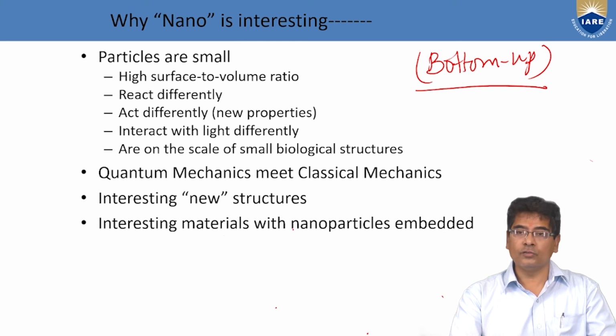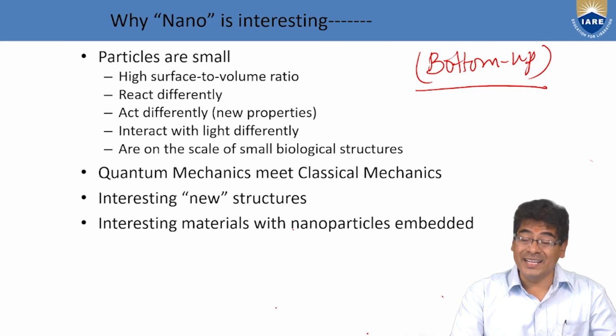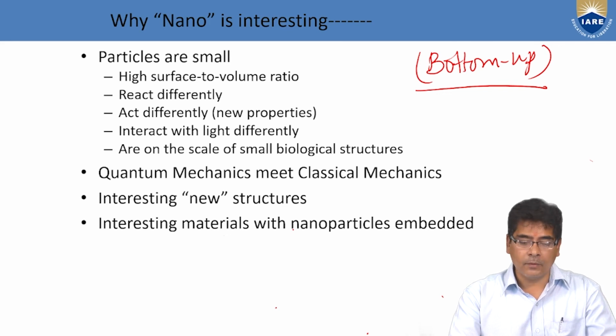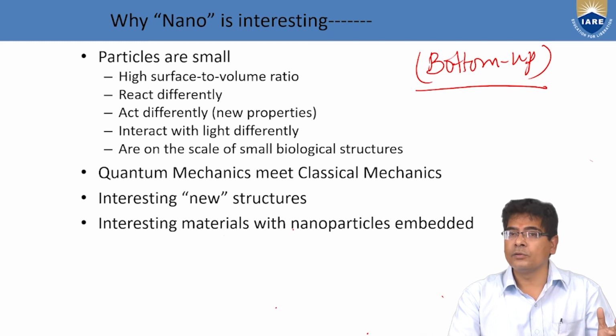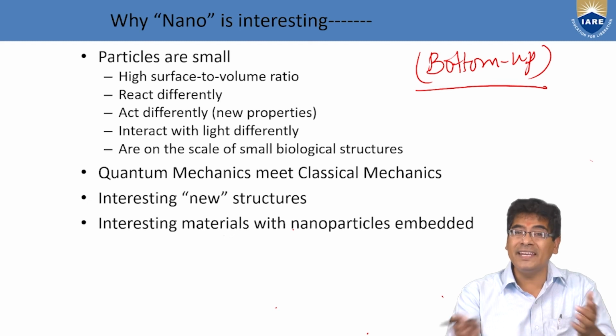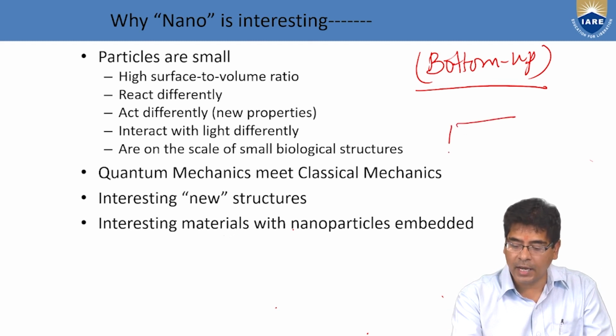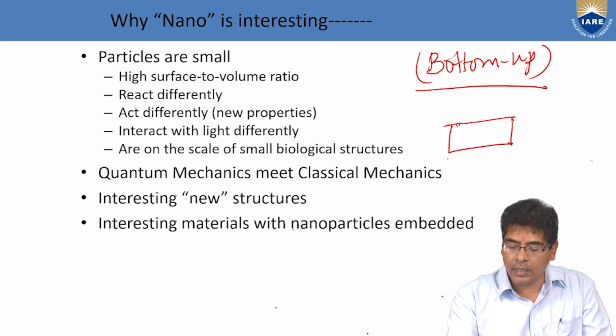The solution is deposited on a suitable substrate by spraying, dipping, or by spinning. It is kept for a while for gelation. If you take a glass substrate and deposit some material,